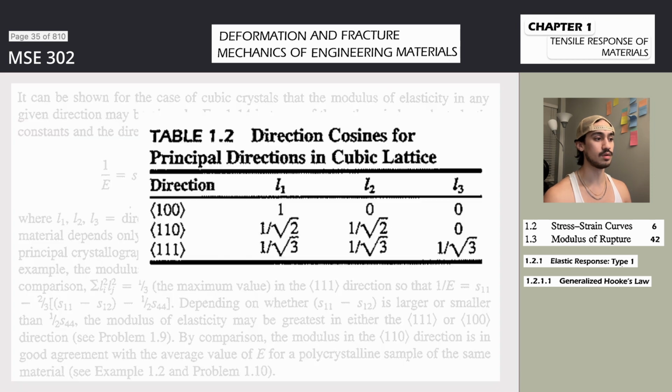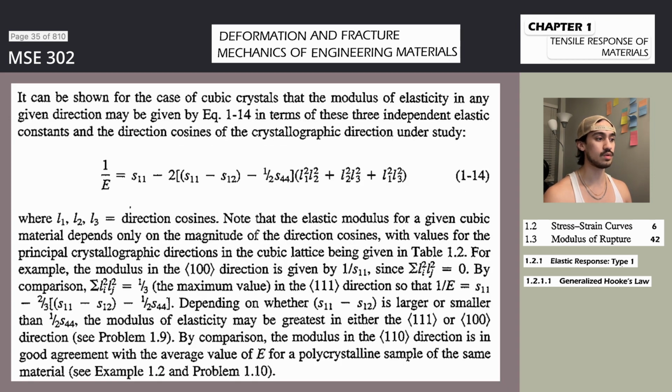A much more important material property is the yield strength, a stress level related to the onset of irreversible plastic deformation. This quantity is difficult to define, since the point where plastic flow is found will depend on the sensitivity of the displacement transducer. The more sensitive the gauge, the lower the stress level where plastic flow is found. In recent years, special capacitance strain gauges have been used to measure strains in the range of 10^-6. In fact, a number of studies dealing with the mechanical behavior of materials in the microstrain region have been undertaken as a result of this breakthrough in instrumentation. These investigations have shown, for example, that plastic deformation, the irreversible movement of dislocations, occurs at stress levels many times lower than the conventionally determined engineering yield strength.